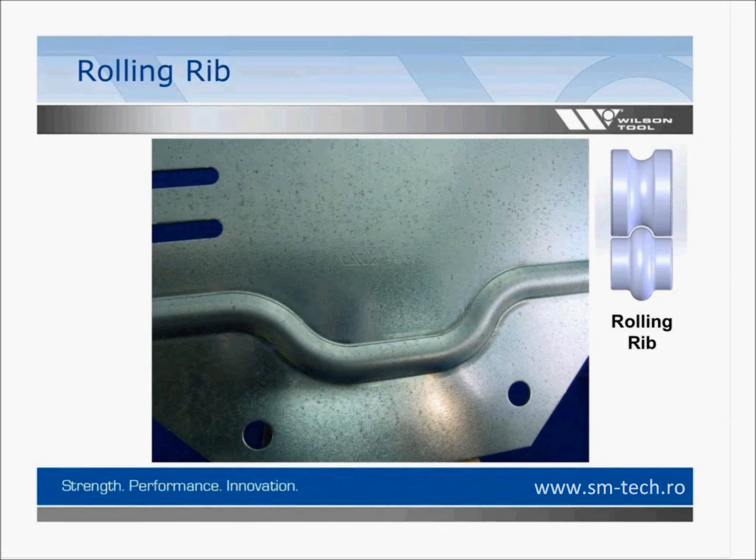However, you don't have to just do straight line ribs anymore when you're using a rolling rib. You can do arcs. You can create lots of different size ribs. The rib wheel is made with the size rib that you want to put into the metal. And that size rib is made for a specific thickness. When we make these wheels, we have the material thickness that you're going to be using in mind.